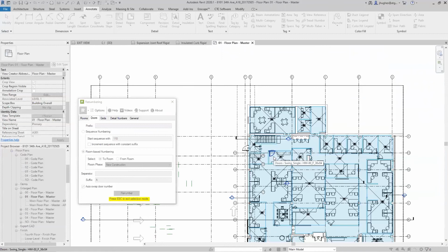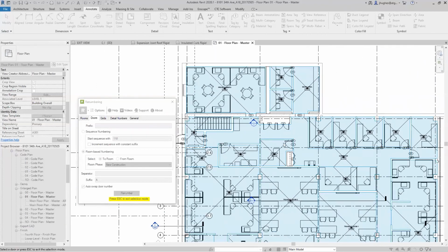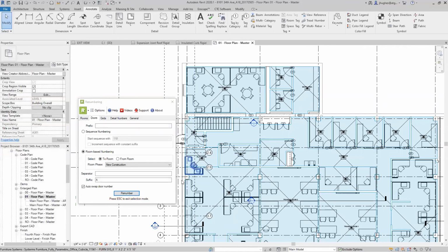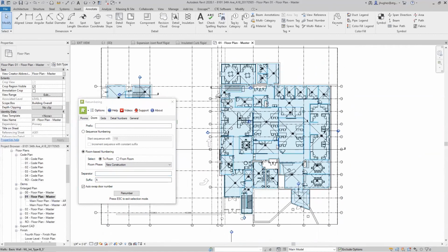I might use that previous quick select tool and isolate just the doors so that I could see them. That would actually be an amazing way to do this and not miss any doors as I'm going around visiting it here. But when you're through, you hit the escape as it tells you to do down here. And now it is out of that modeless state back here where this is now a primary selection. So you can renumber the entire, and I didn't put you guys through that, but you can renumber all of the doors in this floor plan. That's going to save me several minutes and give me no errors on renumbering, especially when I'm doing it by room. That number is not already going to be taken. So it's just going to take care of that for me.